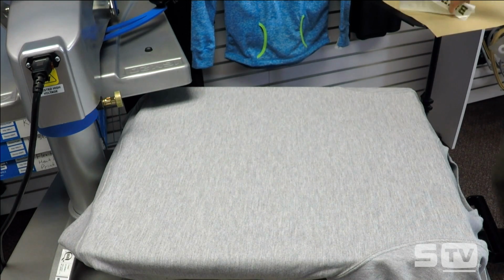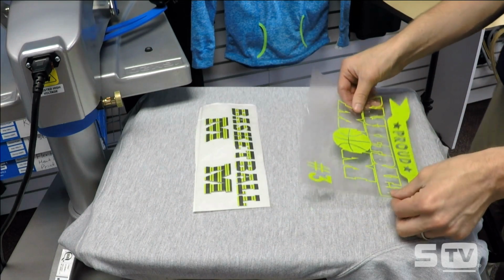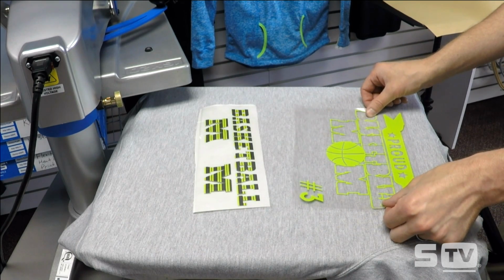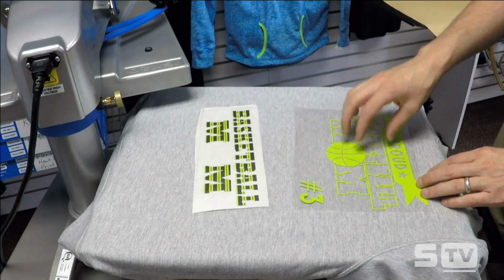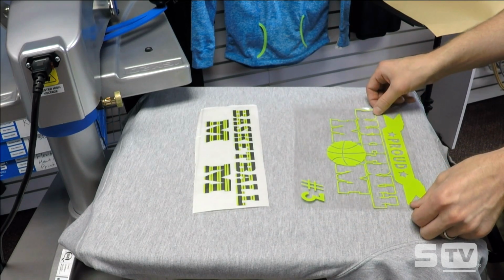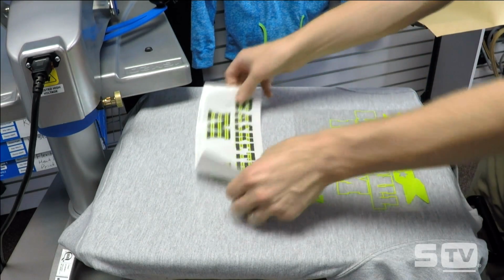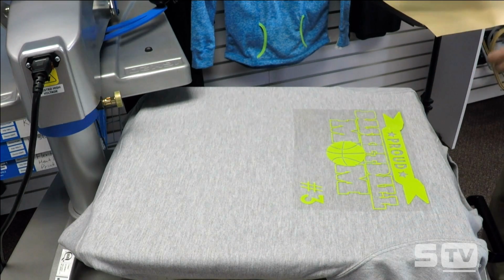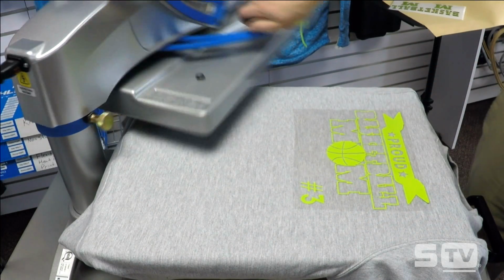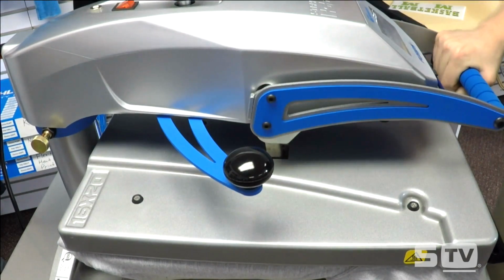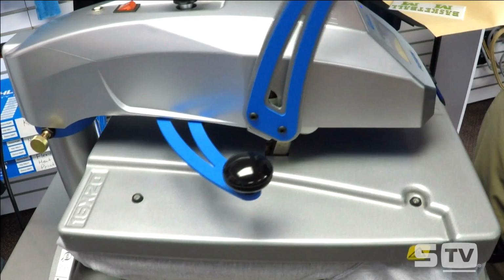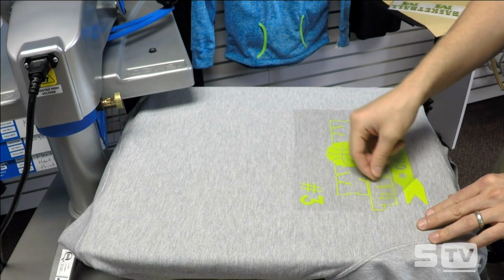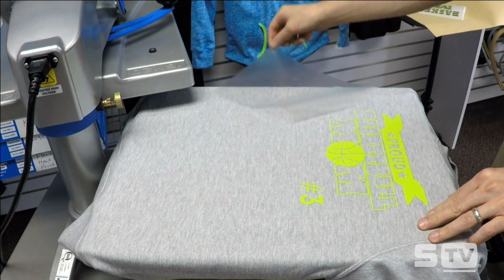Basically, from an application standpoint, we've created this design, and I always like to start with the largest part first. I could really go in any order here, whether I want to do the pattern down first or the fashion film down first. I like to start with the largest part of the design because that's the important thing to alignment, to making sure everything's straight. So I'm going to position that down. Since I'm dealing with fashion film, I'm just going to tack it for a couple seconds. If this were the pattern material down first, which we'll do on our next sample, I would have had to give it 5 seconds to tack it down. I'm going to release the carrier.